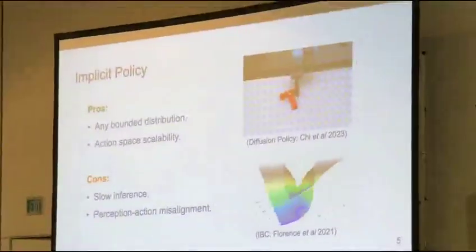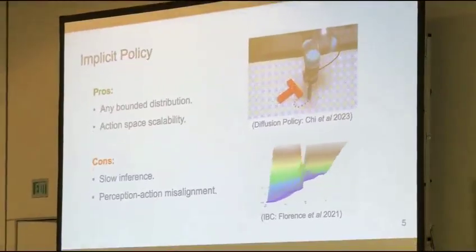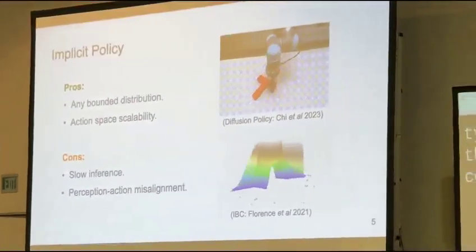During inference, actions are generated by iteratively denoising, effectively performing a kind of gradient descent in the action space. To accurately capture the action gradient field, the neural networks used for score estimation are typically large, which makes the inference process slow and computationally expensive due to the many iterative denoising steps. Additionally, since the learned action gradient field is not explicitly aligned with the perception space, the learning process can be less efficient and the convergence slower than action value maps.